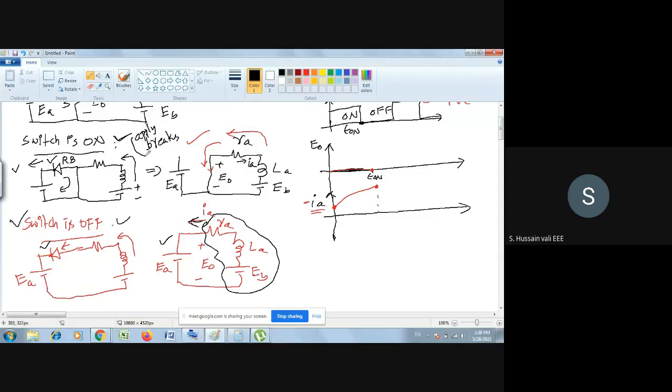Apply brakes. So when you apply brakes, only then will you take the help of the second quadrant chopper. You will do this simultaneously. When you want to apply brakes, you operate the chopper in the second quadrant. Why do you do that? Because the advantage is that the energy in the motor, that is the mechanical energy, you can take it back. That is the advantage.